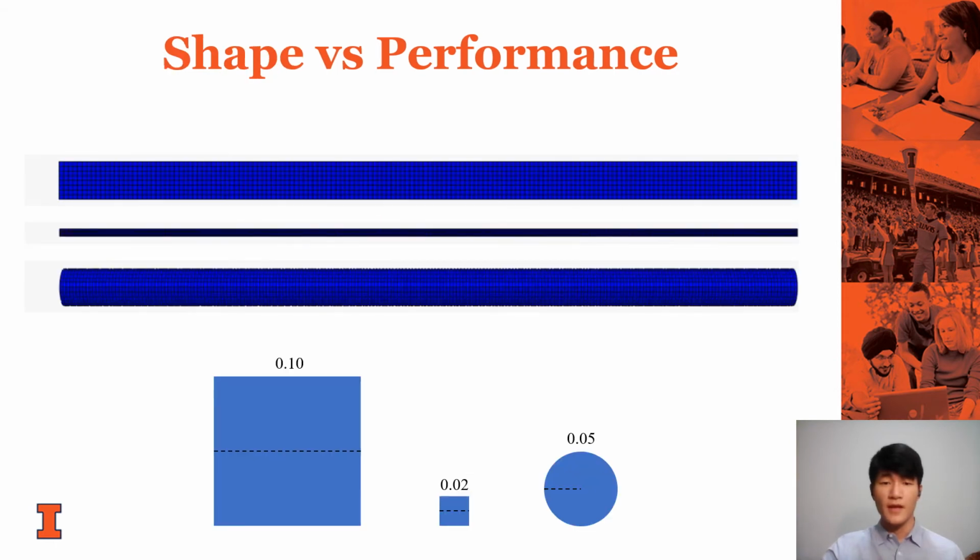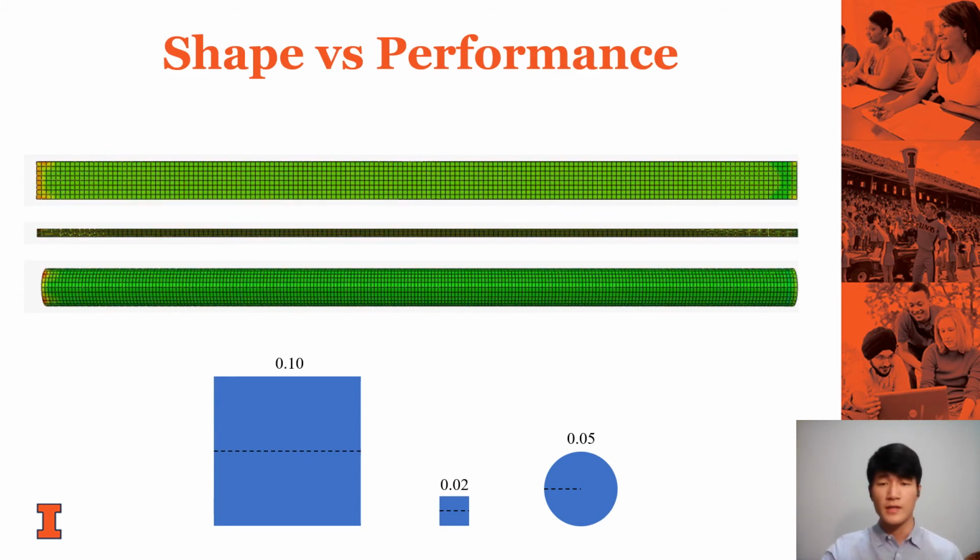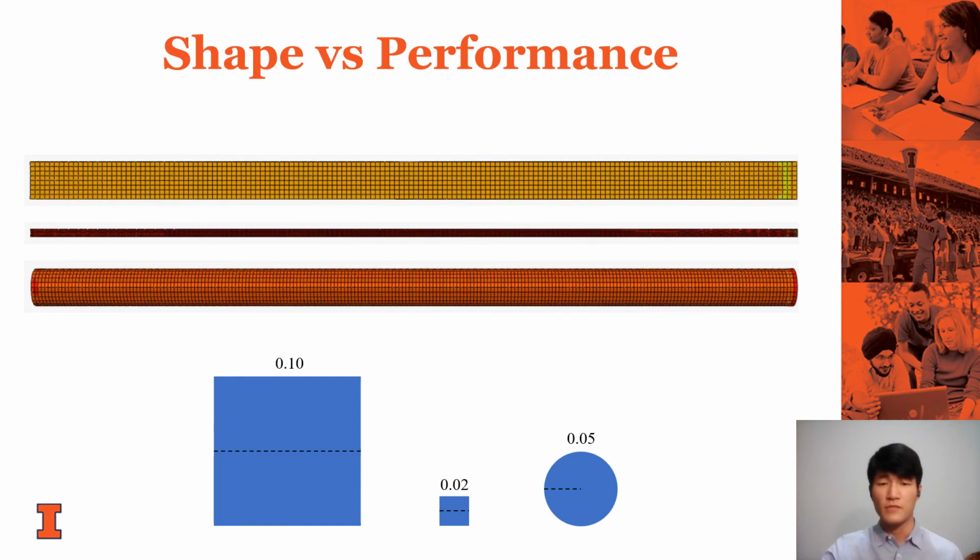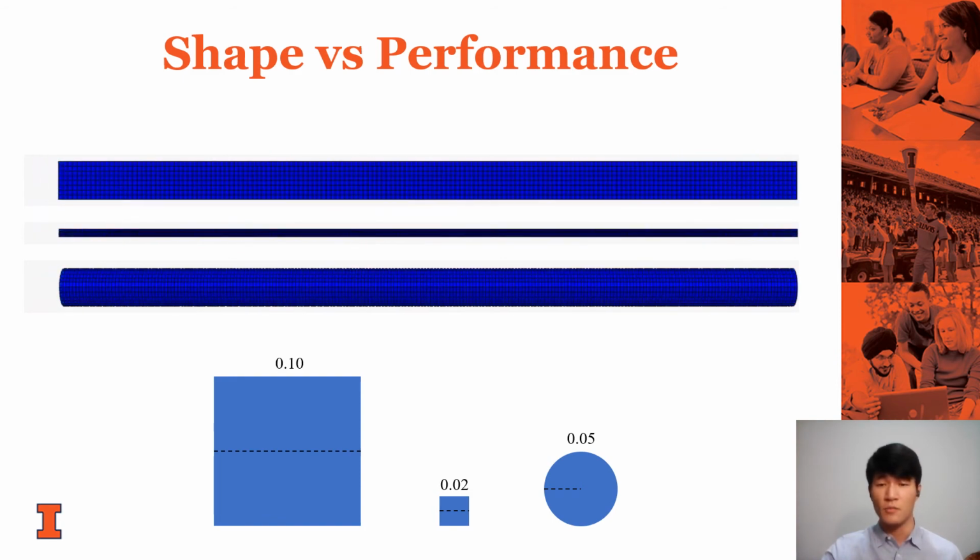In this case, SMA bars and wire that have different cross-sectional shape and area were loaded to find the correlation between the shape and performance of the actuator under uni-axial load. The images on the bottom show the cross-section of each SMA actuator on the top. As shown in the video, the amount of deformation stroke seems almost identical for all three of them.